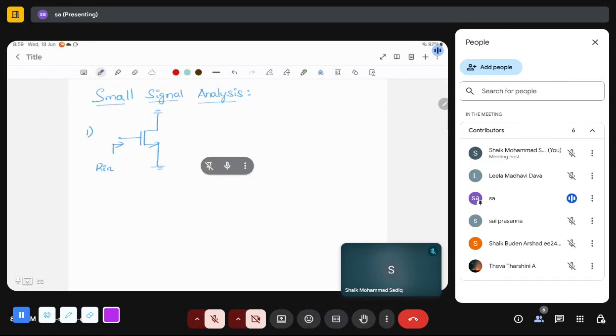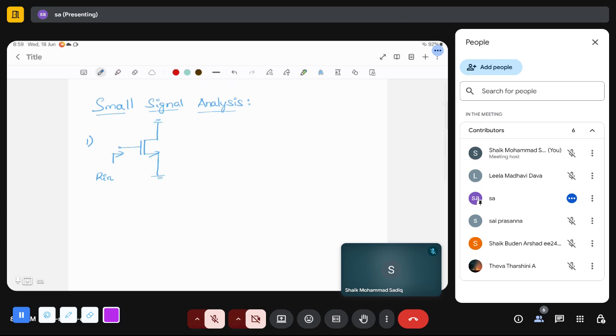For this, what is Rn? Earlier I have said that to find the equivalent resistance of some black box, you have to apply some input potential Vt and find the current flowing from the source Vt.